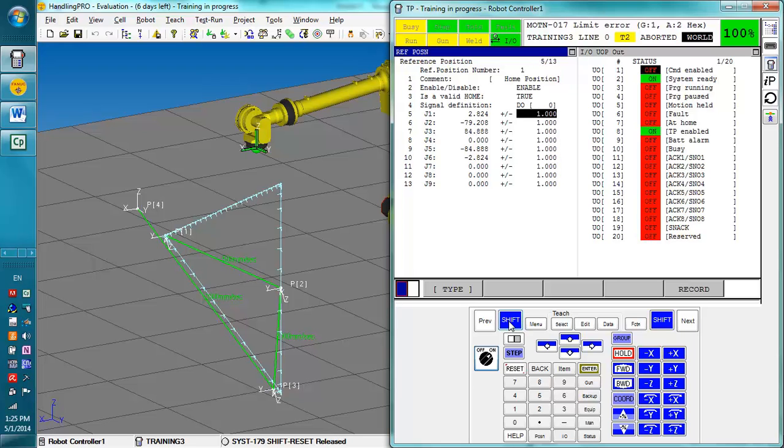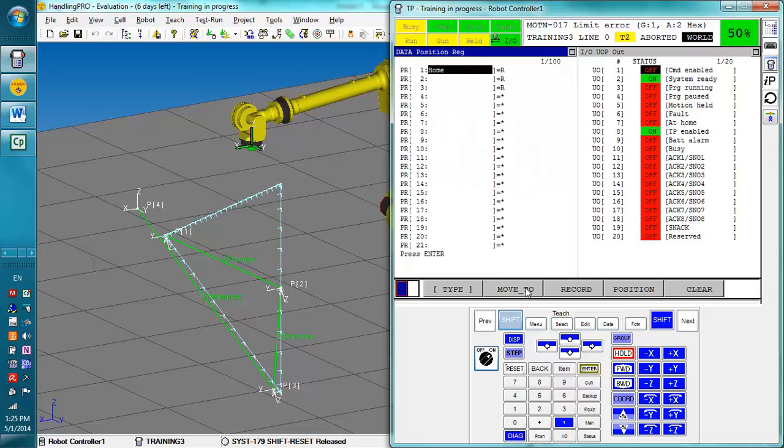For instance, if you just need it to be in this general area, you can just put plus or minus 5 degrees here, and thus if we slow down the robot and move it a little, sorry, we actually have to go back to the home position first, so we are at least in the area. So if we're in this home position here and we just are within the general vicinity of it, this UO will still be on, or our digital output will still be on. So if we want to adjust the tolerance, we can.